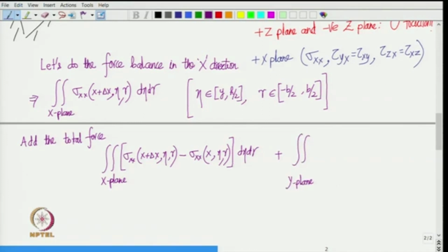and in the x direction the force that is acting is tau x y, but you see it was in the negative x direction, because on the bottom face the shear traction is in the negative x direction. So, it comes with a minus sign, minus tau x y into d zeta d gamma. And where does zeta and gamma vary?